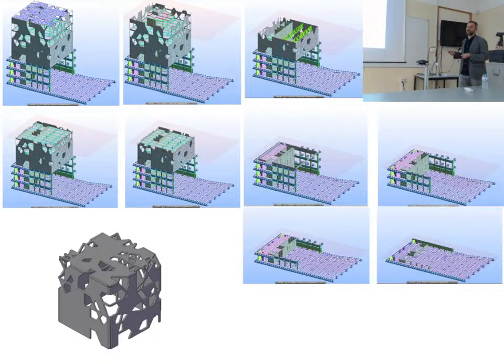And then the box, the main box. This was the most complicated part of the structure. It is 20 by 20 by 20 meters, and in three of its faces we have columns. Then on the other face, the stage, it's not possible to place columns, but it was quite easy since we have 20 meters high of concrete. After you have 2 or 3 meters, it is able to support itself. And we also placed two steel trusses in order to be able to build these two levels on top of the box.